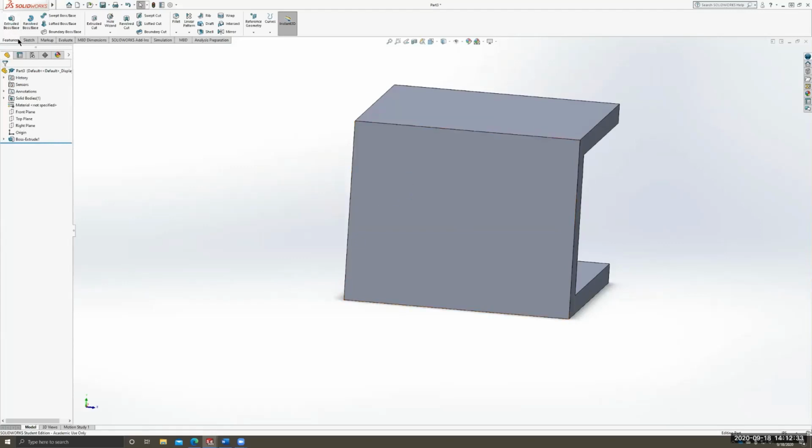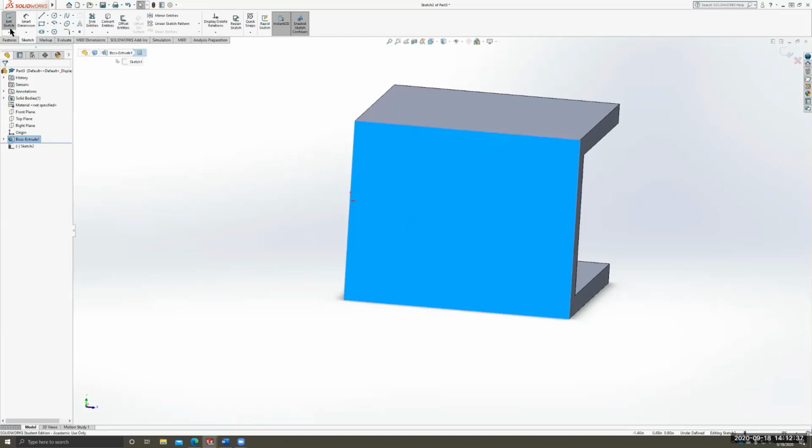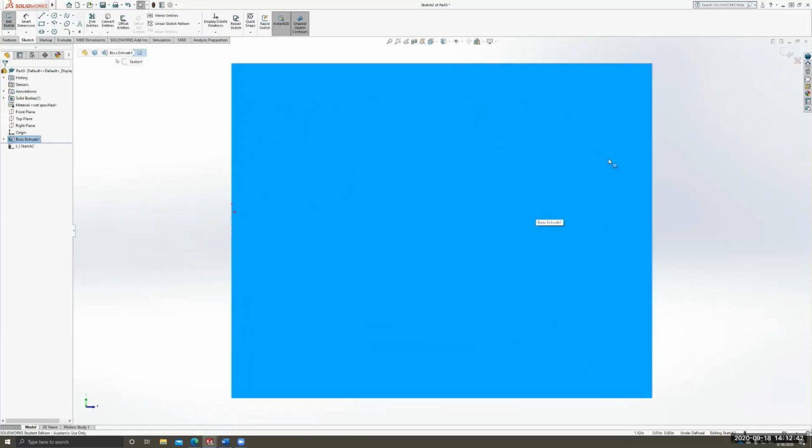Okay, so you can either click it and then go to sketch, or you can hit sketch and then click the face. Control 8 will usually line up the face that you're on. And so I'm just going to make a basic rectangle. We have these rectangle options here. I think I'll use the corner rectangle just because it'll be easier for me to line it up. But you have the 3-point center. I don't ever use these ones. I usually only ever use the corner and the center.